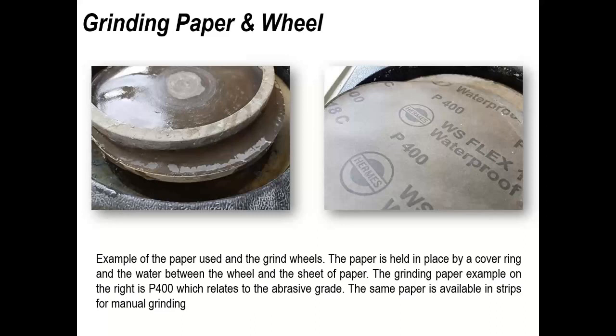You've got papers of a certain grit. So you're buying papers of different specifications, and depending on the numbers on those pieces of paper, that determines the amount of material that would be removed. So if you had something that was 100 grit as opposed to 400, the 100 would take off more material and leave deeper scratches in your sample than a 400.